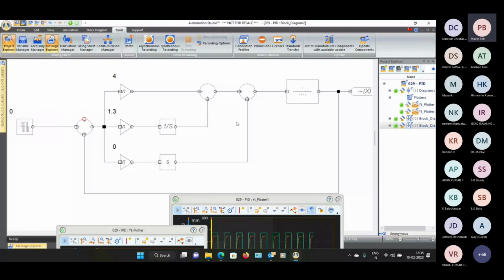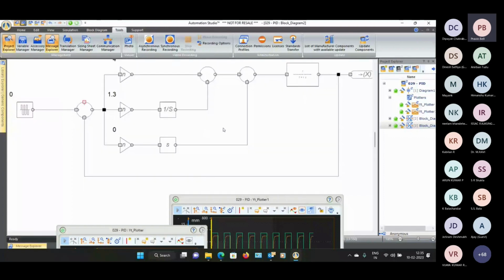So the simulation section is first validated in software like Automation Studio with a simulated control system. If you want to interface, you could work through the OPC channel or use the API. After this is validated, you can try to generate code from this control system. Automation Studio does not allow code generation of this block diagram. You may have to rebuild it in Simulink or LabVIEW.